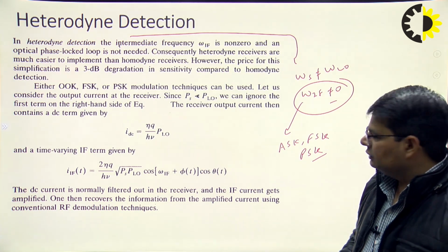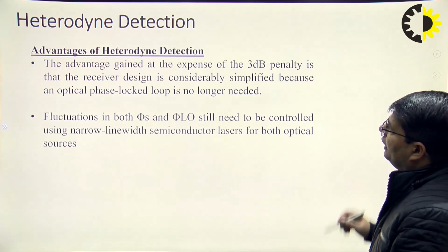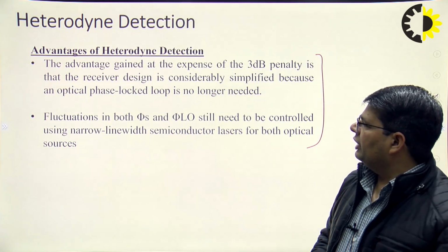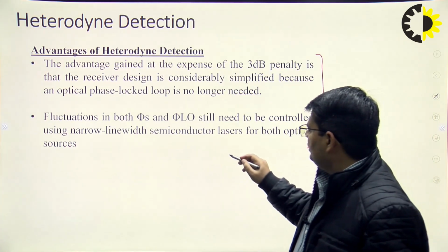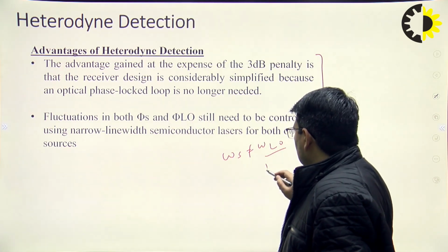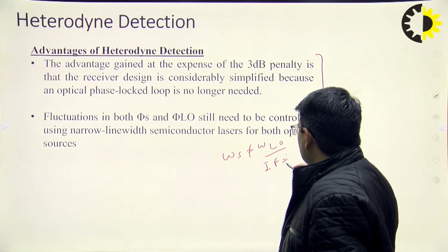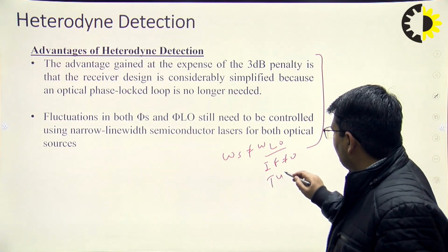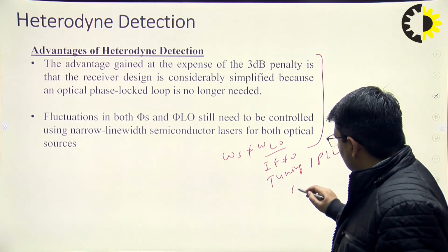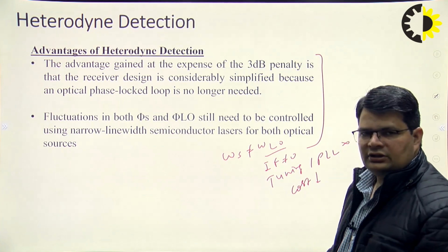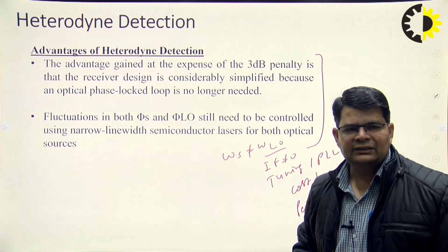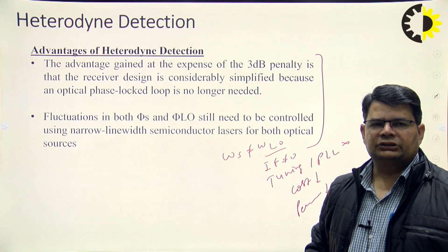And the advantages and limitations we have already studied. In heterodyne detection, there is no requirement of matching, so IF is non-zero. So there is no requirement of tuning or PLL. So cost will be less, but performance will also be slightly degraded as compared to homodyne detection.